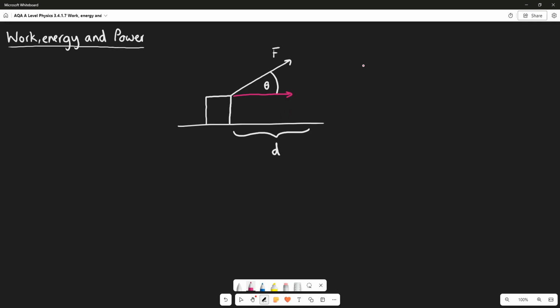As long as the calculation for work is done where the force and the distance are in the same direction as each other, we will come out with a correct answer. We could resolve distance for the direction of force, or we could resolve force for the direction of the distance moved. Either will work.